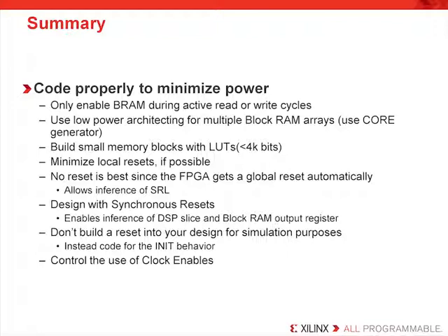Design with synchronous resets. This enables inference of the DSP slice and the block RAM output register, which is good for performance. Don't build a reset into your design for simulation purposes. Instead, code for the init behavior. And then you control the use of clock enables.